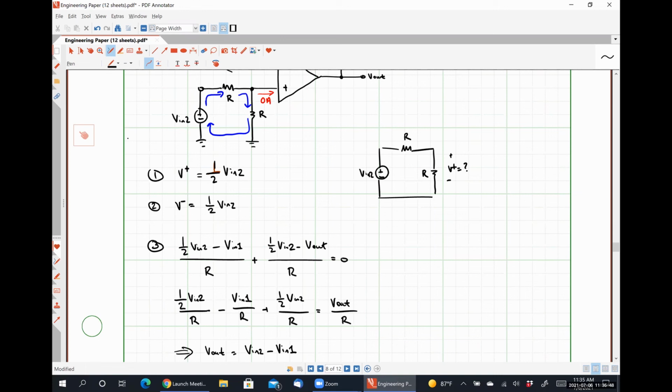I think that is enough out of me for today, and we only have about 10 minutes left of class anyway. So, what did you call this circuit again? A differencing amplifier, because it just takes the difference VN2 minus VN1. Okay. So we could take the difference and then feed it into another amplifier and boost the difference if we wanted to. But cascaded amplifiers are beyond the scope of this class.